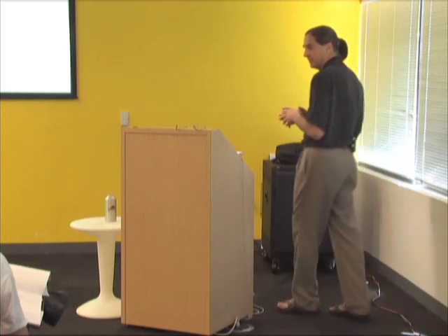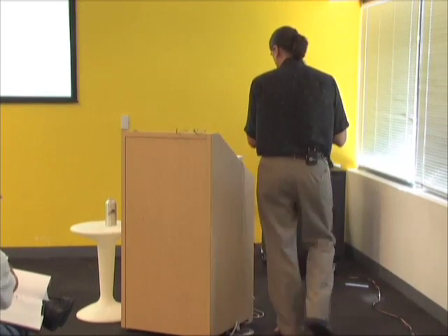Where is transitions? Where do you turn it on and off? I never turn it on unless I absolutely have to. Unless the client begs me to tell them what the solar shadow is going to do. It's just painful. If you're working with big architectural models, you need to sit down, turn on the shadows, look at it. I just recommend not panning and moving around a lot. I mean, you can set up scenes and do movies and do all that, but working generally, you're just going to slow yourself down to nothing.